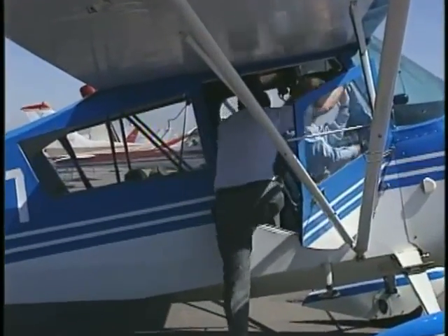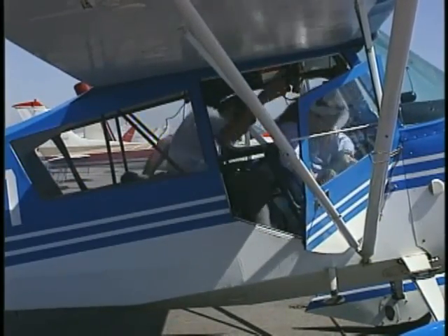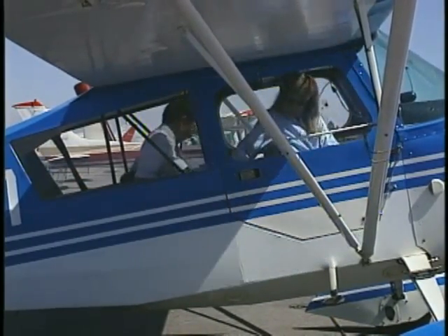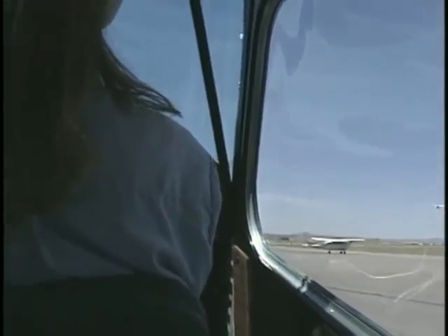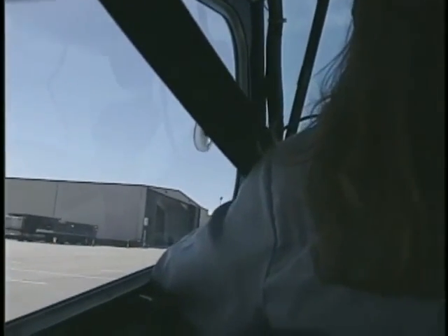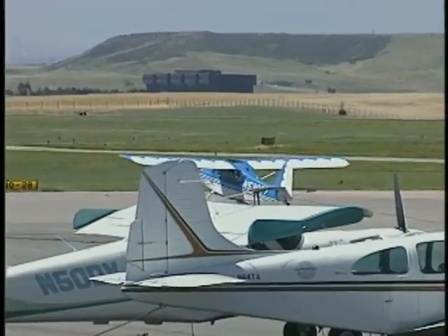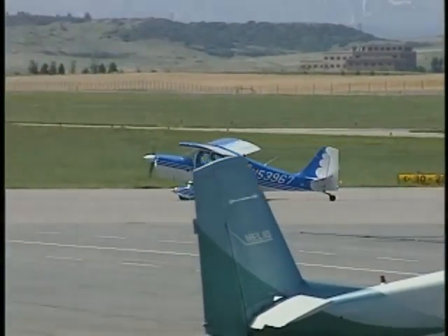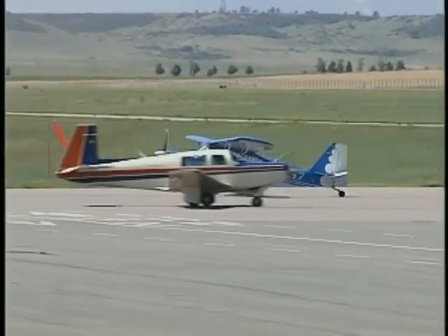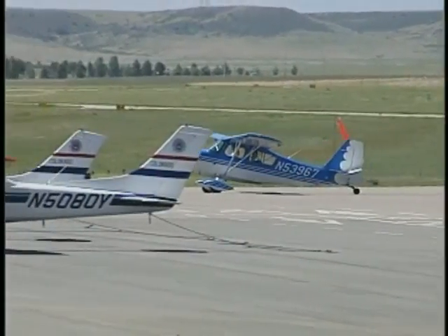During the checkout, you should note any characteristics that may affect how you will instruct in the aircraft. For example, in airplanes equipped with tandem seating, there may be reduced visibility from the rear seat, and communications between you and the pilot may be difficult due to high noise levels. In addition, there may be incomplete instrumentation or aircraft controls for the rear seat. Because the regulations require competency in normal and crosswind takeoffs and landings, wheel landings, and go-around procedures, these operations should be the focus of the tailwheel checkout.